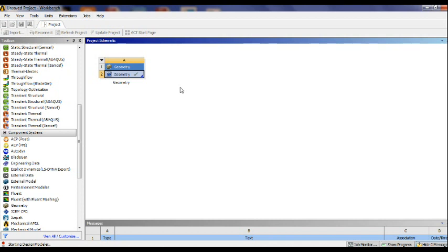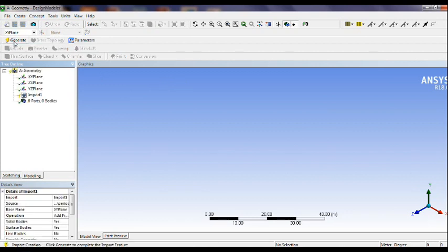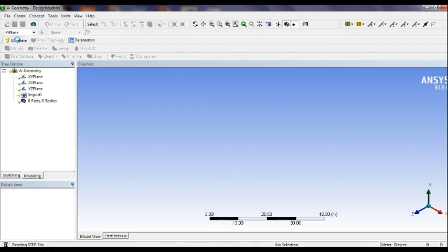in Design Modeler we will define the boundary definitions like inlet, outlet, then the wall, symmetry. In the previous example we had seen that we used the rectangle geometry of tube banks. Once it is open, click on generate,